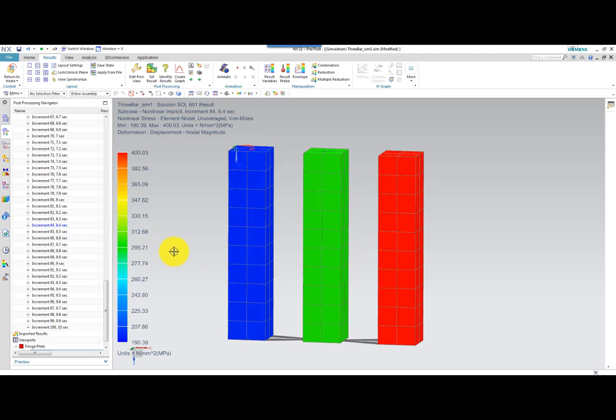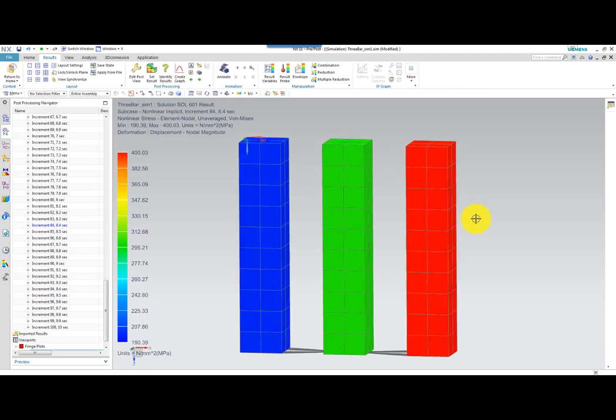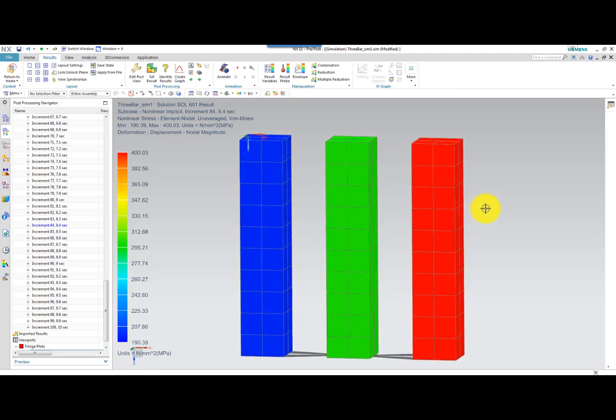And now they all are in the plastic region, and they have all lost their structural stiffness. And they have gone through a change in tangential stiffness from 3EA over L to 2EA over L. And then finally, when also beam 3 has gone into plasticity, it has no more structural stiffness, and it doesn't increase its load capacity. So that pretty much wraps up my intention with this simulation, how to show how material plasticity will influence the tangential stiffness of a system.